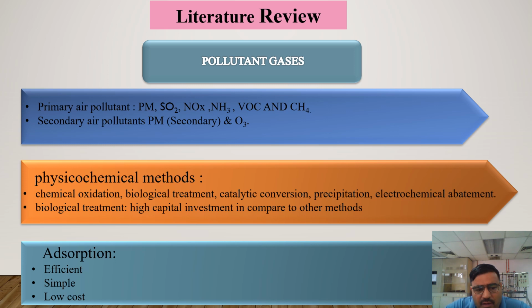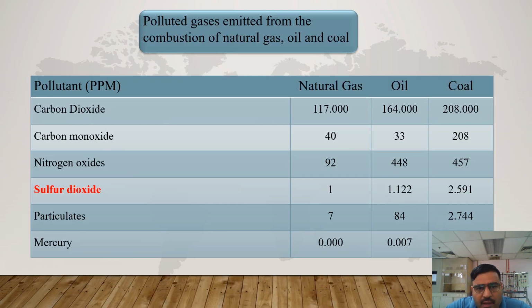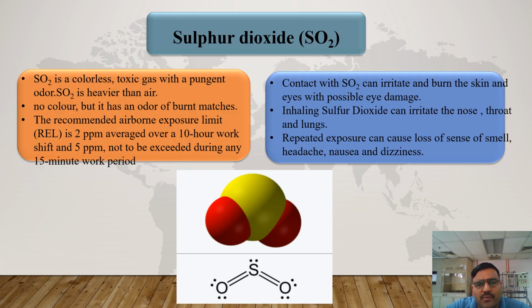Adsorption is efficient, simple and low cost. These are the pollutant gases emitted from the combustion of natural gas, oil, and coal. Sulfur dioxide is a colorless, toxic gas with a pungent odor. SO2 is heavier than air, has no color, but has an odor of burnt matches.